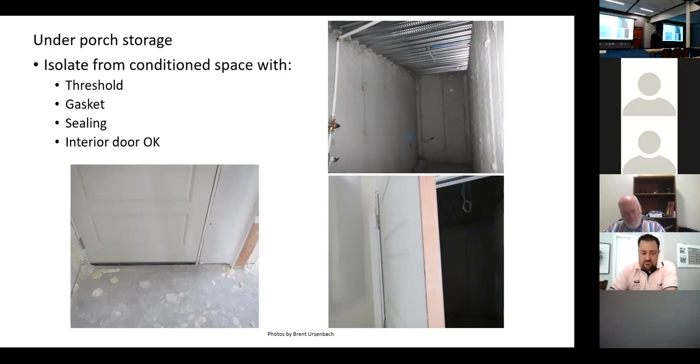If you go to ASHRAE tables or Manual J tables and you take a standard interior door with the 2 masonite panels and the airspace, and you come up with a U factor for it, or an R value, it's going to be better than 0.32. And so I'm okay with the interior door simply because of the airspace and the product. And it makes sense, doesn't it?